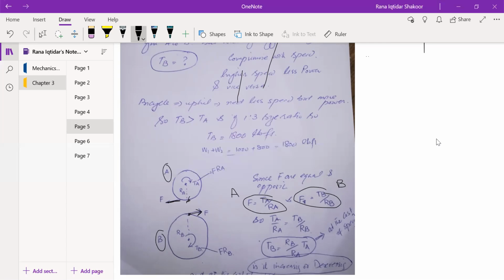If you just visualize what sort of gears will be in the gearbox of a car, then definitely the gears for gear 1, gear 2 should be larger in size because they are meant for larger torque but lesser RPMs in comparison with the gears being utilized for third, fourth, or fifth gear in a car, right?